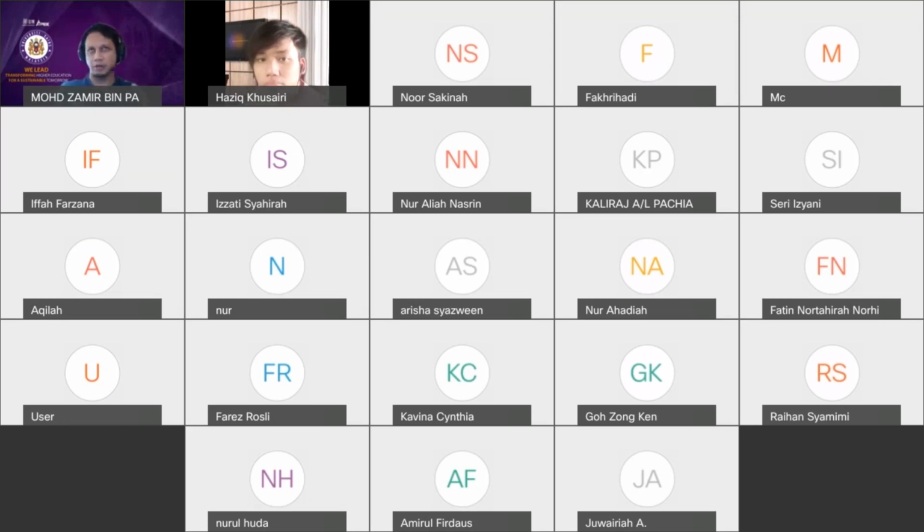Contoh kalau you buat oxidation, then you'll probably be assigned to do wet oxidation with certain parameters on 100 or 111, for example. And then you need to do the measurement of your oxide thickness on the microscope, characterization as your visual inspection, compile the data, present as in operation meeting, factory operation meeting, and I'll be the CEO, something like that. Then I'll ask you on the data uniformity, defects. Saya akan set you up macam operation punya ni lah.